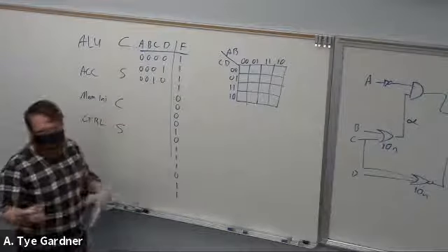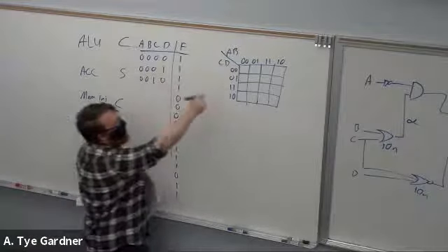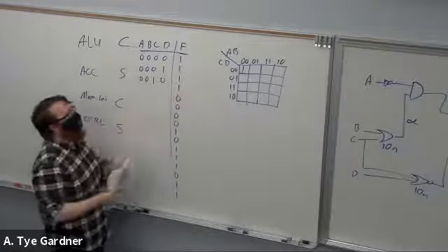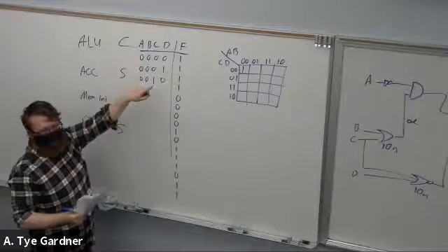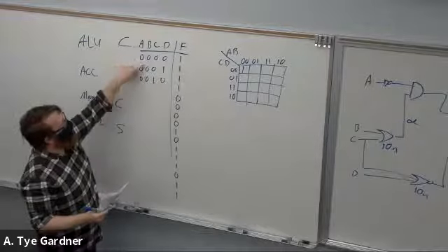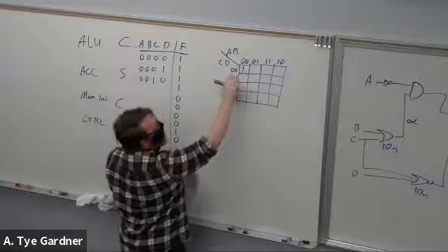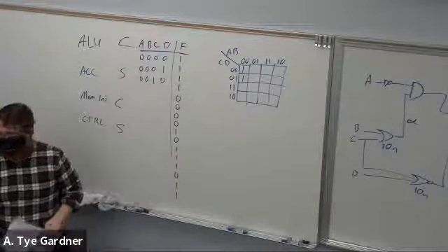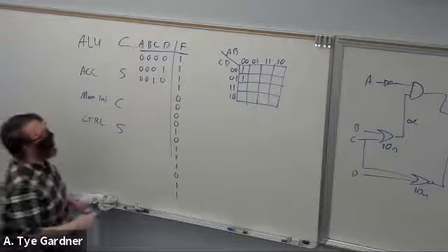Then we just fill it out. The way I like to do it, to make sure I'm not crazy, is that 0, 0, 0, 0 is always here, and it's a 1 in this case. Then I find where the next one is based on the order of the inputs. So it's 0, 0, 0, 1 for A, B, C, D. That's that one. Now I know the direction this K-map is going, and it's super quick to fill in the rest as long as I don't screw up any rows.